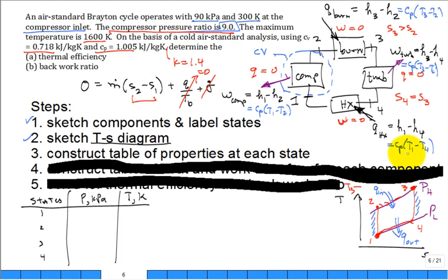All right. What does that subscript P on the C, the specific heat, mean? Constant pressure, right? And then you learned about C subscript V, constant volume. They look at the process for this heat exchanger going from state 4 to state 1. Is that a constant pressure process through the heat exchanger, 4 to 1? No problem there. Okay. Let's take a look. Going 1 to 2 through the compressor. Is that a constant pressure process?